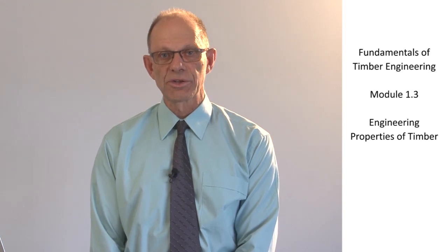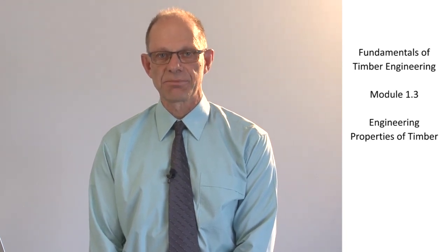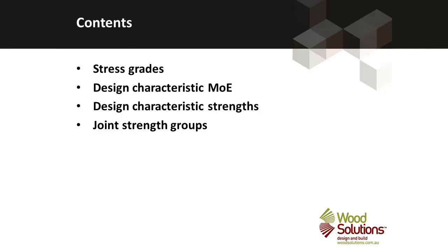In this module, we look at the engineering properties of timber. Timber is an engineering material, and like all other structural materials, it's characterised by properties. So we'll look at these properties. These properties are indicated by a stress grade. And of interest to us as structural designers is the characteristic modulus of elasticity and a suite of structural strengths.